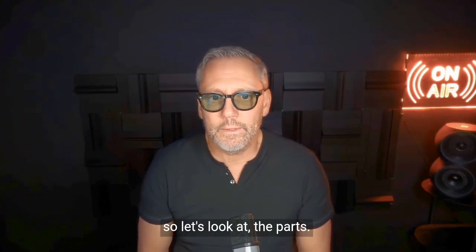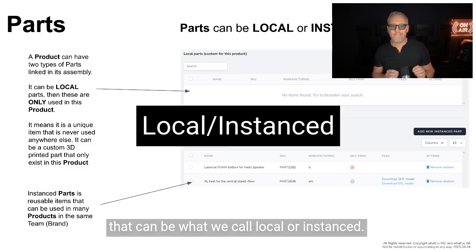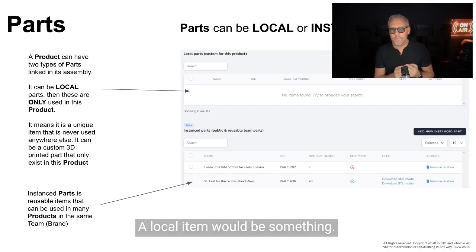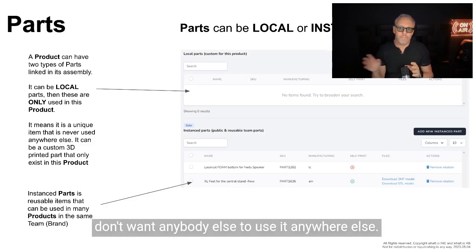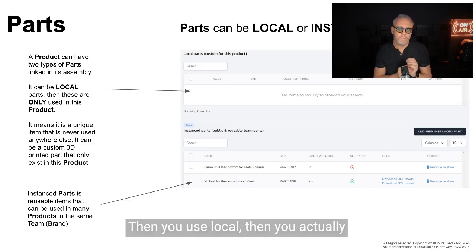So let's look at the parts. We have two different kinds. They can be what we call local or instanced. Let me explain why you would do a local item. A local item would be a part that only exists in a single product, and you don't want anybody else to use it anywhere else. It's an individual local component that cannot be repeated anywhere else. Then you use local, and you define that part for the actual product.